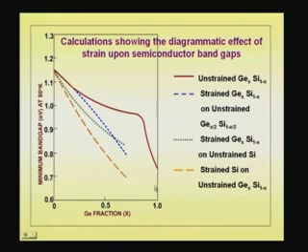the top curve. Germanium 0.72, silicon slightly more than 1, in fact people talk of 1.11, 1.15, that range. So, this curve shows it varying from about 1.15 to 0.72, it all depends also on what temperature you are measuring at. But what we are talking of now is silicon germanium which is strained. The top layer is unstrained silicon germanium. So, when the layer is strained, the lattice is under stress and the energy band diagrams also undergo changes, and because of that you get a different band gap. In fact, you get a lower band gap.